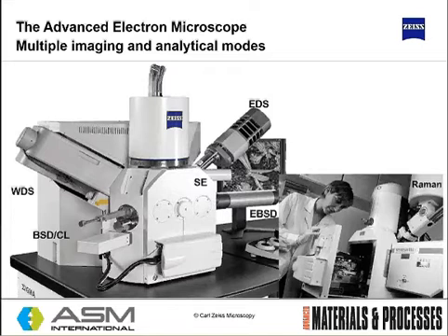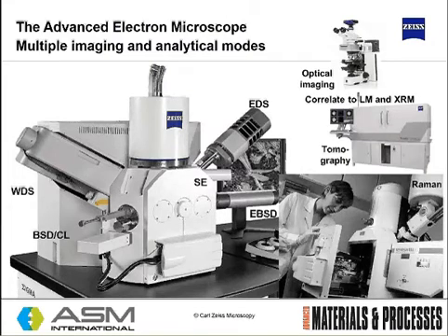You can also integrate Raman spectroscopy, which opens up new opportunities in analysing not so much the metals themselves, but more the oxidation and corrosion products of the metals, as well as the chemical analysis, not just an elemental analysis, of the inclusions themselves. And of course, as we said before, the optical imaging and X-ray imaging can also be used to correlate either the LM with the SEM, or indeed the XRM to the SEM, which is the highest resolution.